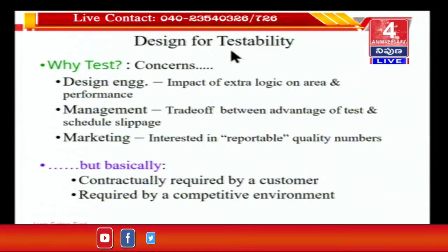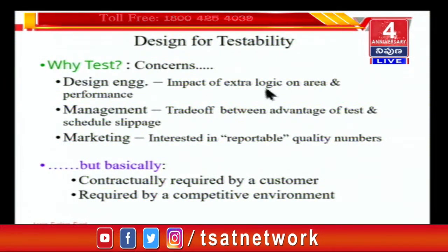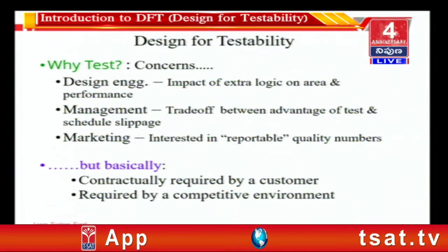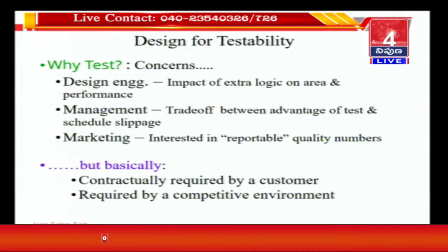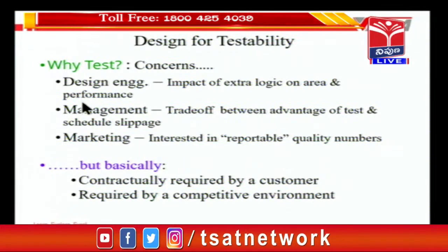The design engineering group will say that there is an impact of extra logic, the impact on area as well as performance in terms of timing, and power, of course. Whatever logic is modified by the test engineers will remain on the chip and go for manufacturing. It is not something that the DFT engineers will do at the time of their job, and then the logic will go away. No, that logic actually sits on the chip and goes through the manufacturing stage.